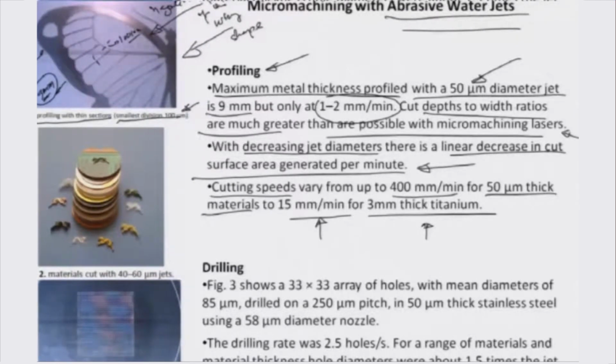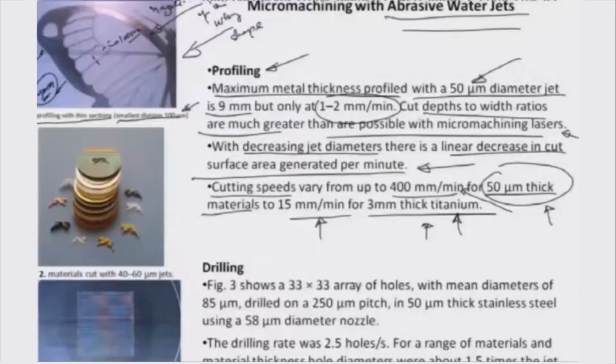and as you can see here, the cutting speed is higher, meaning thereby that the depth of cut of the material is lower. Okay. One of the reasons, of course, is that you have less dwell time on a certain area, and as you are moving ahead you are covering more in terms of length, but the depth that the jet is able to reach is lower because of the lesser impact time that the jet has on one particular area of the surface, and vice versa. You can see that the thickness has increased to 3 mm because of a lower cutting speed.